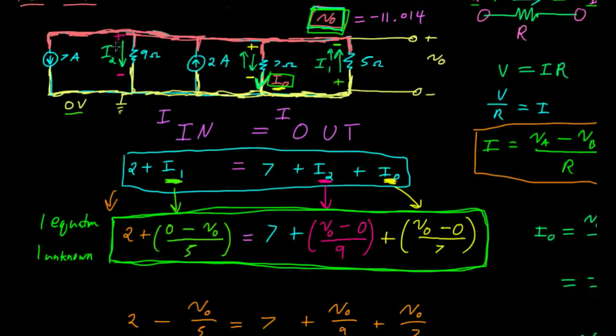So hopefully, I should get rid of that. I'm going to get rid of those arrows just because I don't want you confusing them, thinking I'm redefining my currents I1, I2, and I0. But hopefully that makes somewhat intuitive sense, that I'm pushing more current into my ground node of the resistor. I'm pushing 7 amps of current into the bottom of the circuit, and this current source is really only pushing 2 amps back out. And you should also think about, could I have possibly combined those two current sources, or would it have made sense to do that?